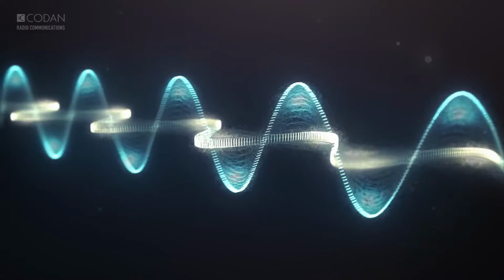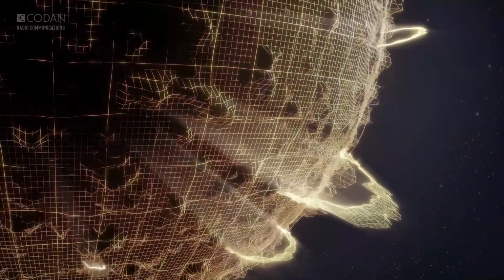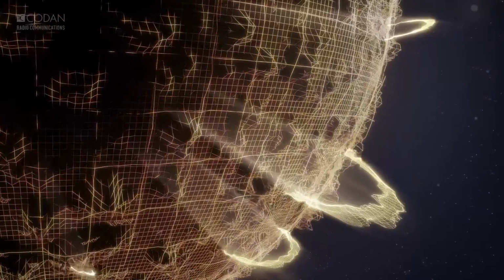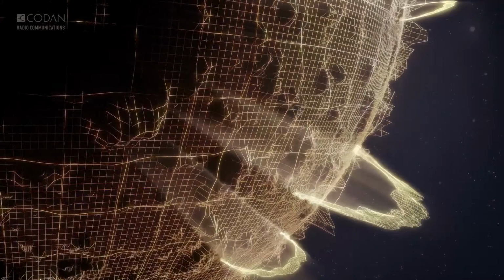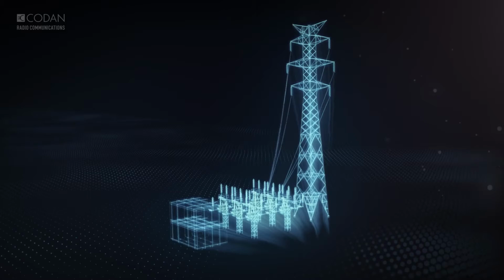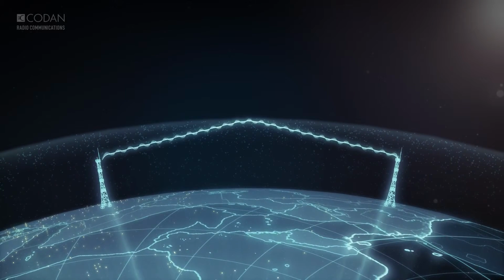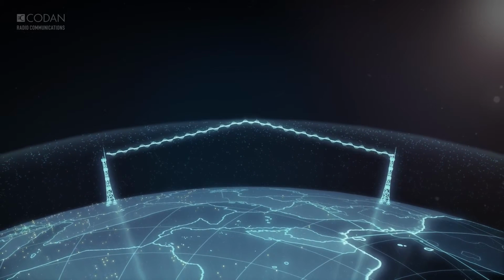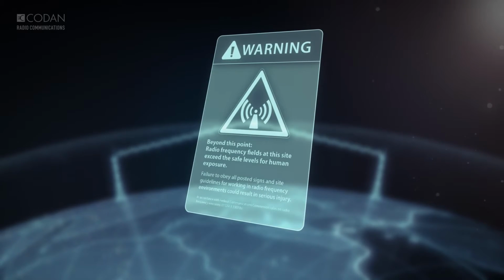What are some of the other factors that can affect HF radio waves? Solar flares can alter the refracting property of the ionosphere. 11-year solar cycles can either hinder or improve the HF radio waves. And finally, something man-made, such as power stations, which produce electrical noise, can affect the reception of HF signals. Apart from these factors, communication through HF radio waves depends on a few other things, like location, local radio rules and regulations.